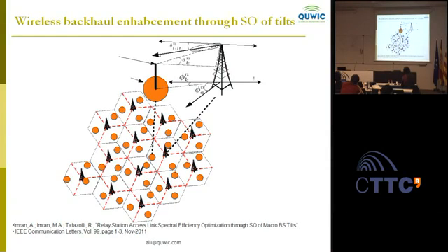Yes. So what we are trying to do through this solution is that here is our base station. It has some antenna, and we want to set the tilt value which would optimize the average spectral efficiency of all the users, or the average efficiency of users concentrated on any point. Irrespective of whatever, if the users were here, they were already getting say 2 bits per second. If they are here, they were getting 1 bit per second.